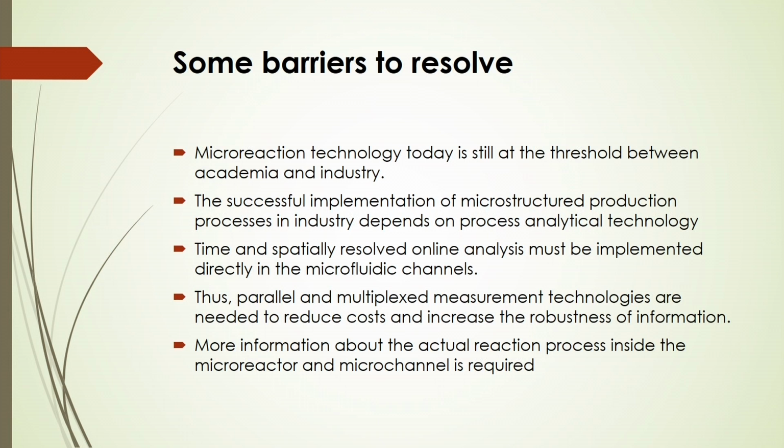There are several researches going on on how to overcome all these problems or barriers. Some barriers are the implementation problems of micro reaction technology today. The successful implementation of microstructured production processes in industry depends on the process analytical technology, because you have to analyze whatever product is coming out. Online analysis of a microchannel based reactor may be very difficult.